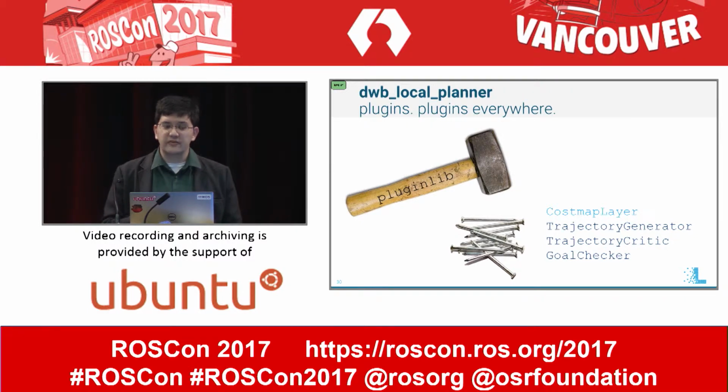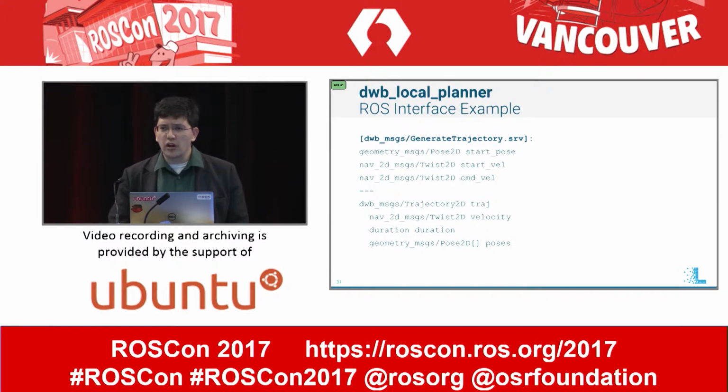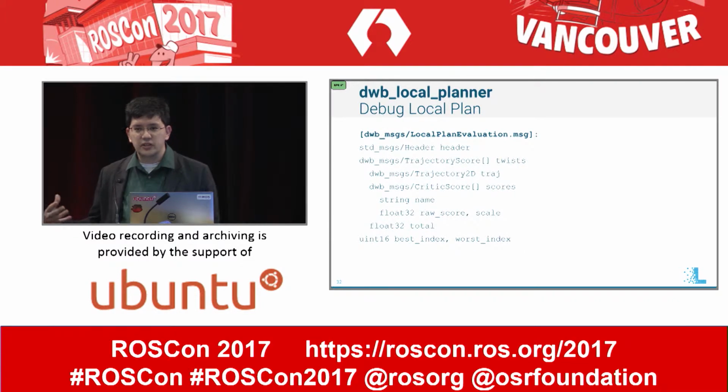But in addition to the plugin interfaces, we also have ROS interfaces for each of these. So the generate trajectory also exists as a service that you can call, where you give it a start pose, start velocity, and command velocity, and the result is a trajectory series of poses. Similarly, while you're planning, you can also generate this local plan evaluation message. And that has all of the trajectories that were generated, the poses that they go through, and the scores from each of the critics for each of the trajectories. And that way, when you're sitting there afterwards and it's like, why did my robot do this? You can actually go back, check the logs, and see.